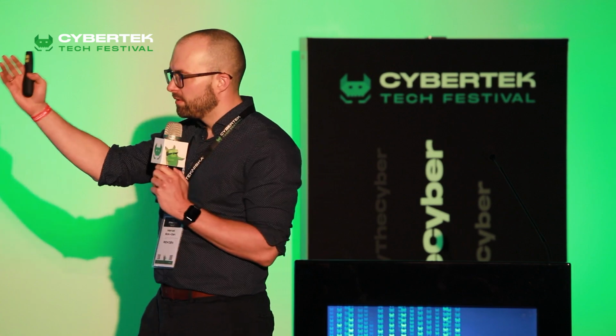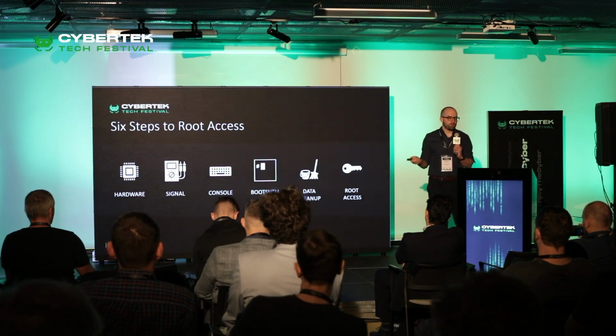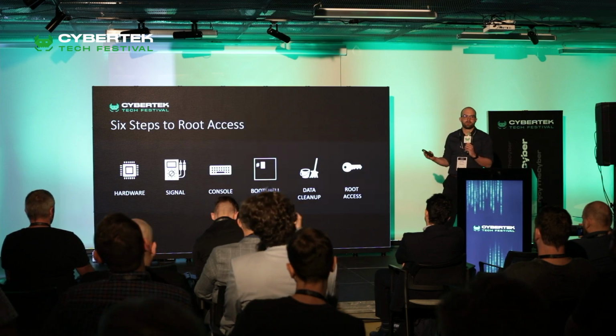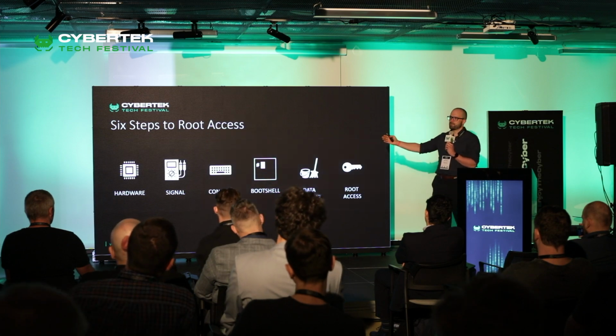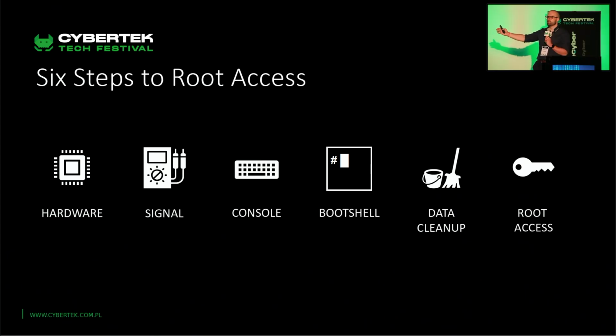You only need roughly 30 euros of tools. You need a digital multimeter, screwdrivers, prying tools, a USB UART interface, and a USB logic analyzer. And if you have that, it only takes 6 steps to gain root access to a device. And this is what we are going to do now. We are looking at the hardware, we're measuring the signals, access the console, break into the boot shell, dump data, clean up the data, and then enjoy root access. Let's start with the first step.